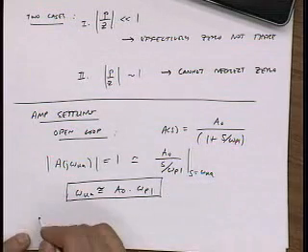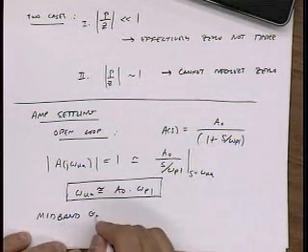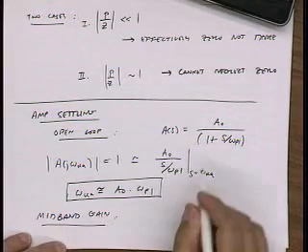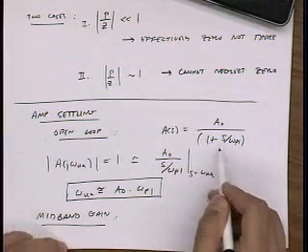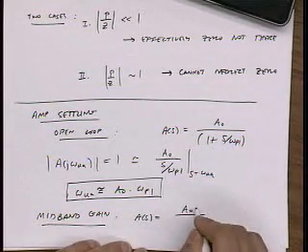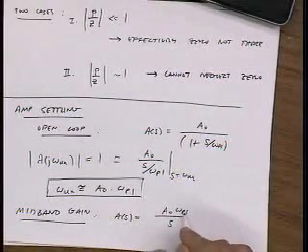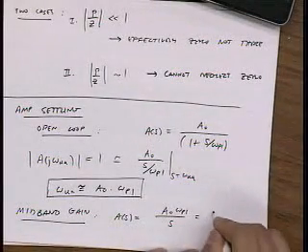Okay? And if I'm interested in midband frequencies, then the gain, when this term is bigger than 1, is simply A naught omega P1 over S, and we just found that A naught omega P1 is just omega UA.